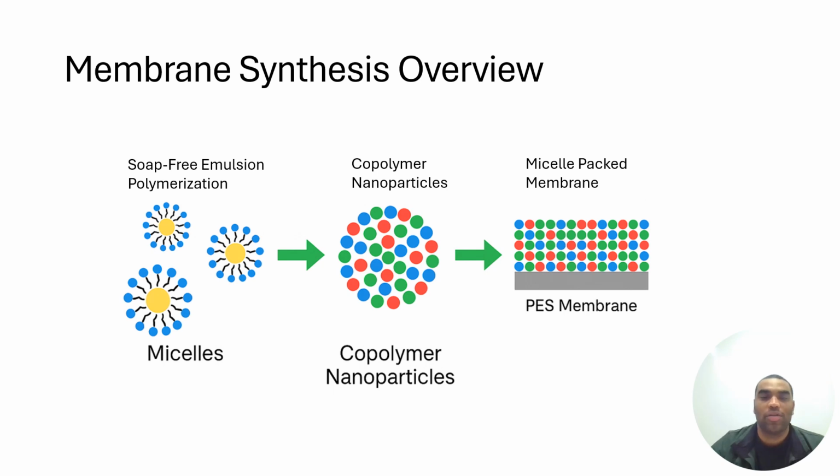From this process, three distinct nanofiltration membranes are produced, each classified based on their DMC content. First is the 1.25 DMC-PES, which contains the highest DMC ratio, which increases hydrophilicity and surface charge. Second is 0.75 DMC-PES, which has a medium DMC content with balanced filtration and charge properties.